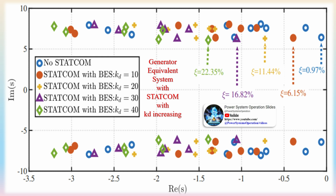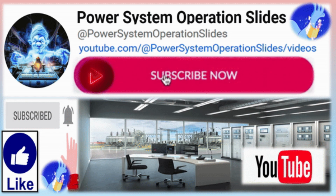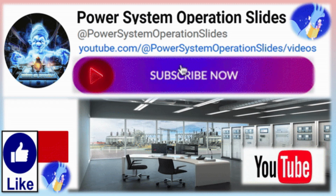This compares the proposed damping controller with the conventional PI-type damper under the same gain parameter. As can be seen from the black arrow, the oscillation of the proposed strategy is less than that of the conventional method, indicating the superiority of the proposed strategy.